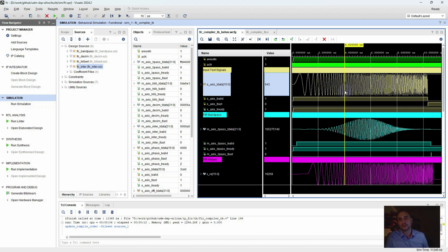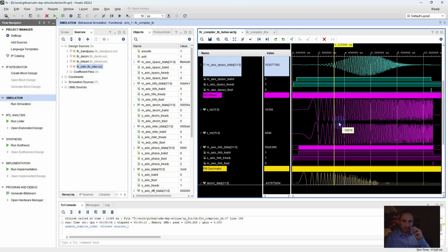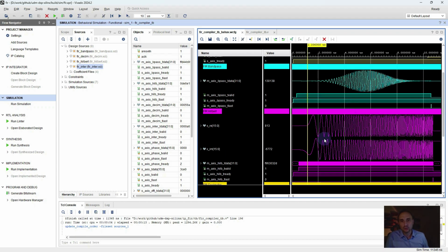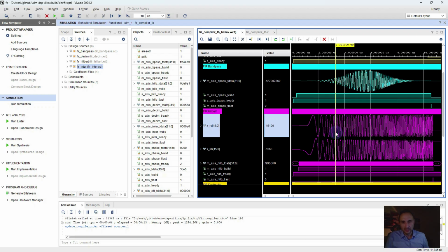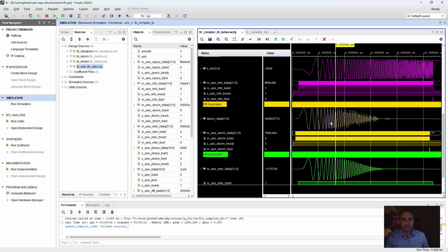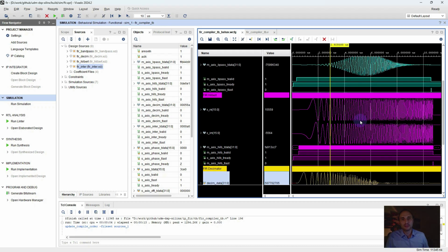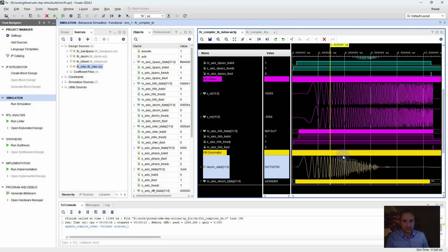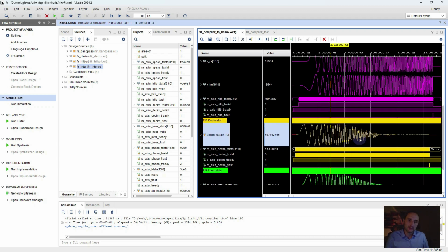Here I have the input signal, a chirp signal, then the bandpass that I already mentioned, then the Hilbert transform. Here I would like to pay attention to the amplitude: the amplitude of the input signal and of the output signals from the Hilbert transform is the same, so there is no amplitude distortion. This is the decimator. With a decimation factor of 4, if you have a sample frequency equal to 100 megahertz, it will be reduced to 25, and therefore half of 25, it's 12.5 megahertz, is what the frequency response will use. In this case, all harmonics that exceed 12.5 will be filtered out.